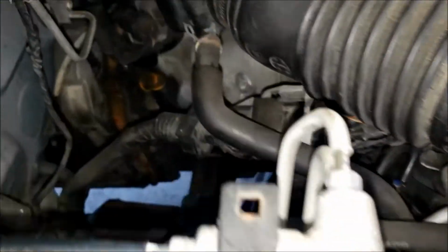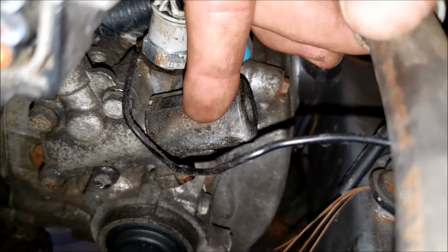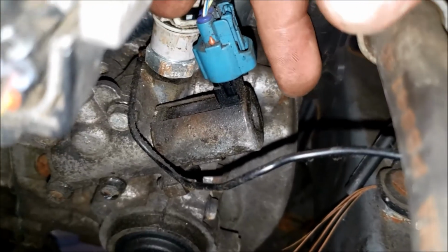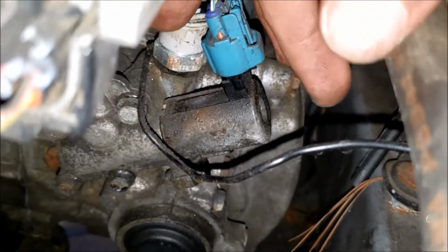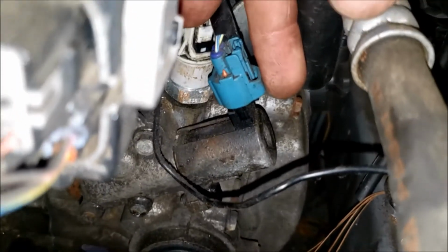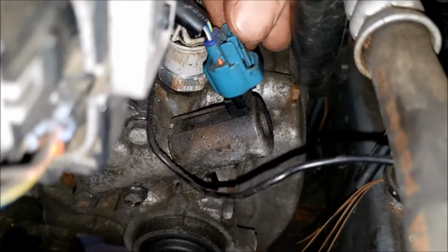So taking a look at the bank 2 side, let me get you a good view of the components. On the back of the cylinder head, this is your VVT solenoid, and this is the VVT oil pressure switch. Now you can see this switch is actually newer, and this is the most common problem. So in this video I'm going to show you how to test that switch. But first, just showing you here how to get these connections off, since I already have the other side off.